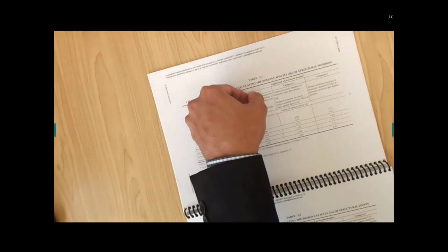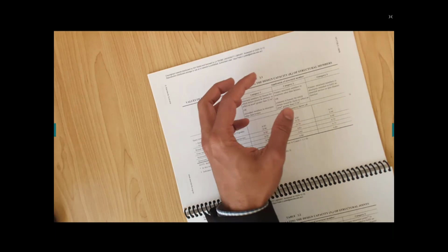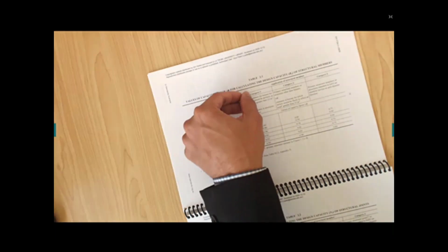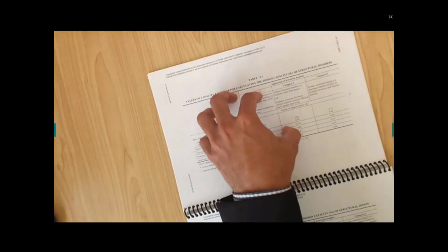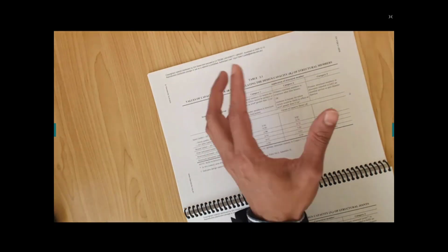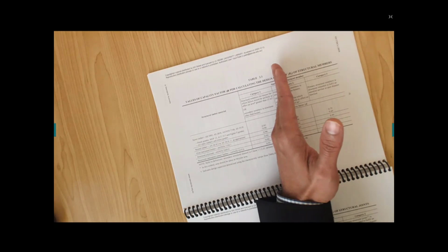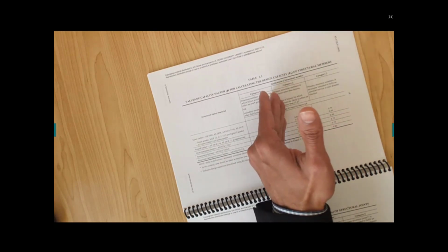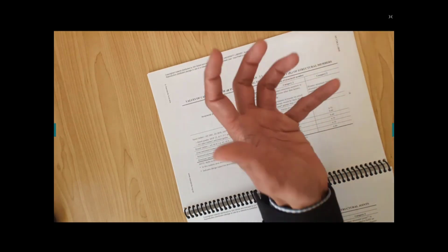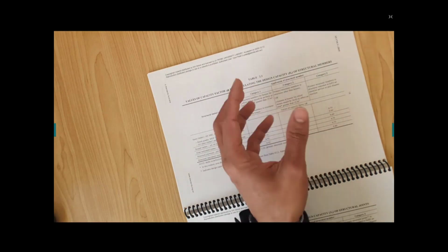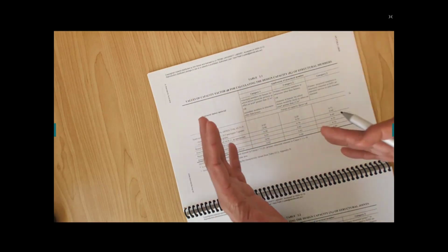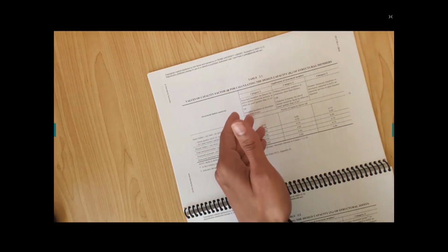Now there are different categories given. In category 1, as I mentioned, where you have secondary members of your structures, if this fails, then only 25 square meters of area of your home or structure would be affected. Category number 2, when you have primary members, and they fail, they will affect more than 25 square meters of area. If you have a bedroom of 5 meters by 5 meters, then it is only affected that much.